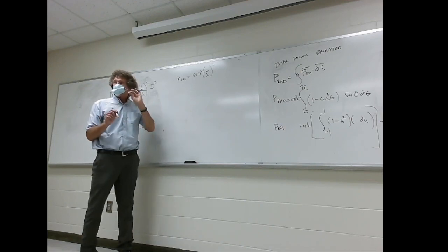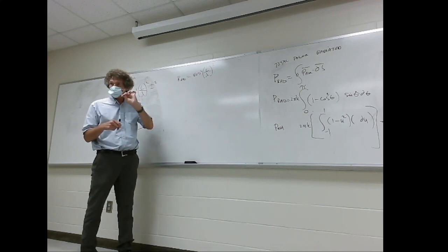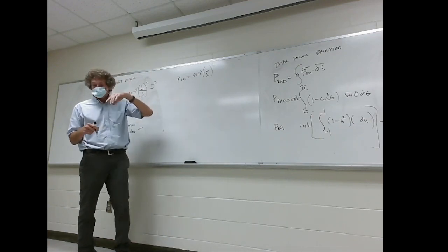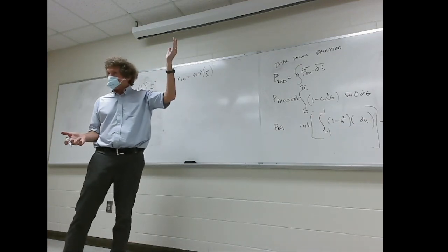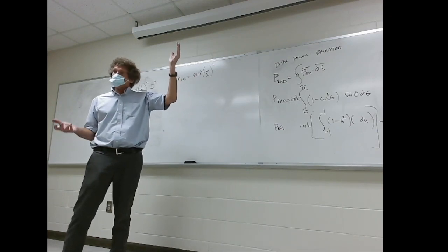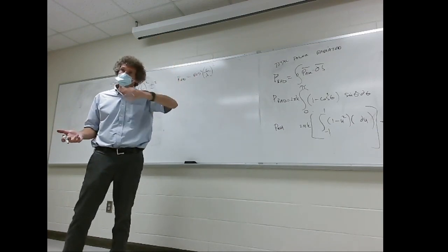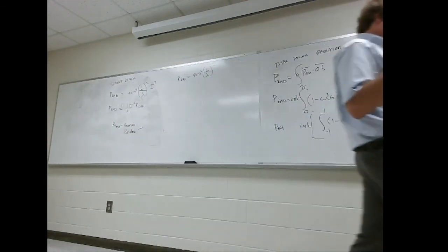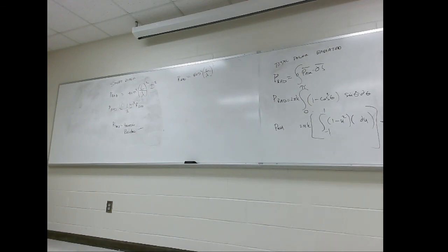Y'all follow me? So one of the problems with short dipoles is they have a very low driving radiation resistance. You got to put a lot of current in to get anything out, and that's not good because current means heating up of the wire, which means power loss. You would like a lot of power without much current. That's the reason your power lines have such high voltages when they carry current long distances, because power is proportional to V times I, high voltage, low current, low loss. So same thing with antennas. We like low loss, or we like a lot of power, which means we want a high driving point impedance.